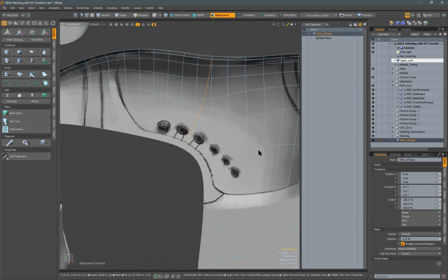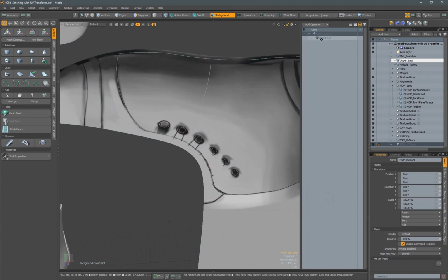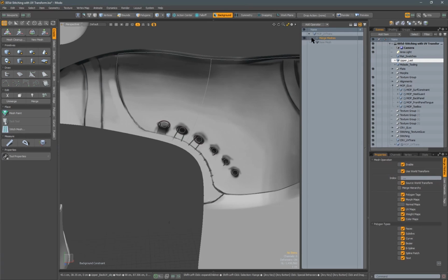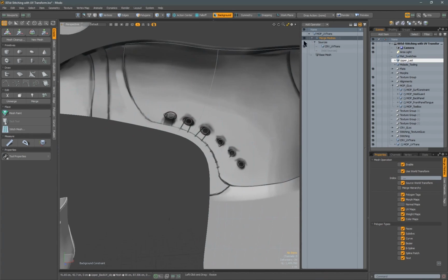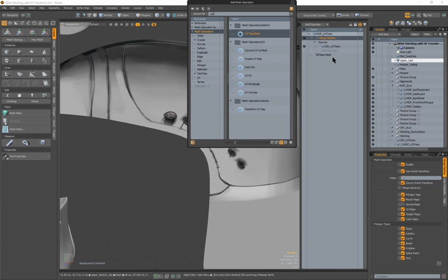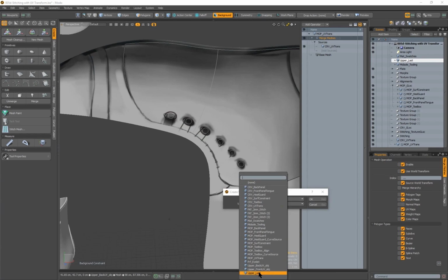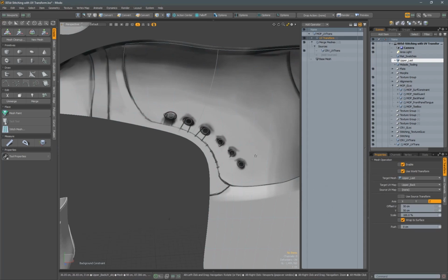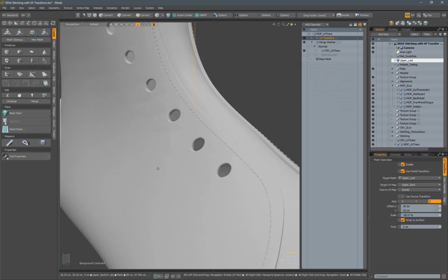All right, now that we have that, let's create a new mesh item. We'll call this mop UV trans. And we'll add a merge mesh. In the source, make sure that we select the right curve. In this case, it's UV trans. And then add an operator UV trans, of course. So we'll select the last and the upper back UV, because that's the flat version we're working on here. And it should show up on the mesh over on this side.